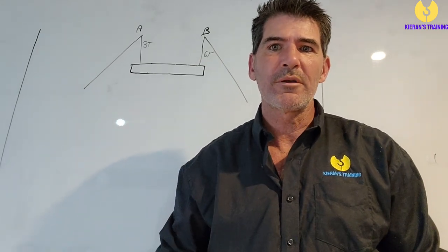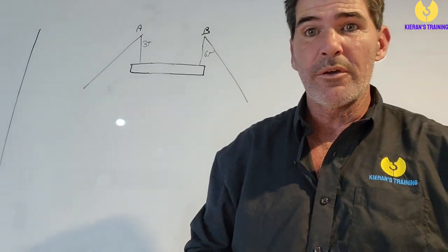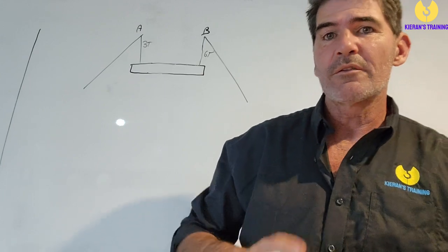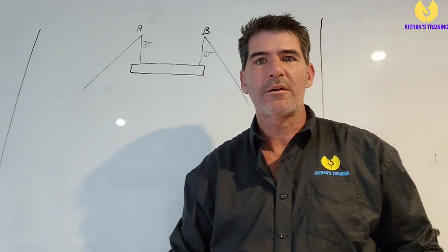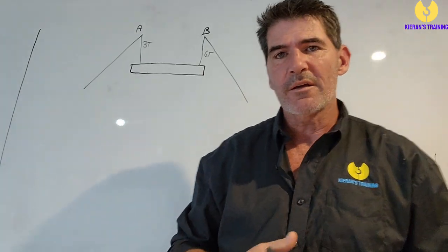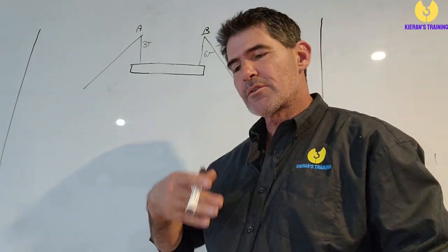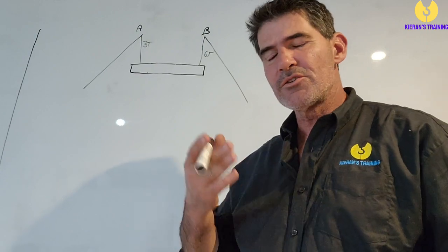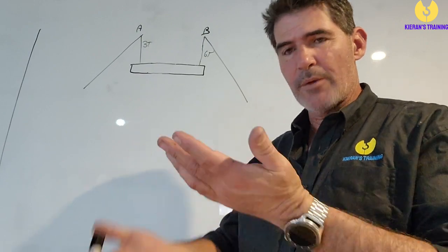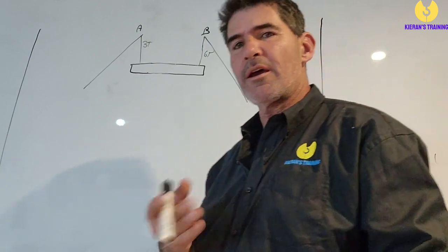So today we're going to be looking at the calculations required for intermediate rigging. The first aspect of intermediate rigging we're going to look at is doing multiple crane lifts. When we're doing multiple crane lifts we need to allow for extra loading. The load share on the crane is going to change as they're roping up at different intervals. The load can change.